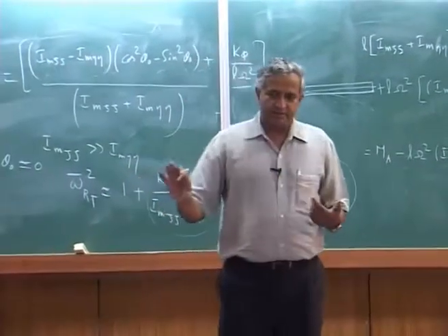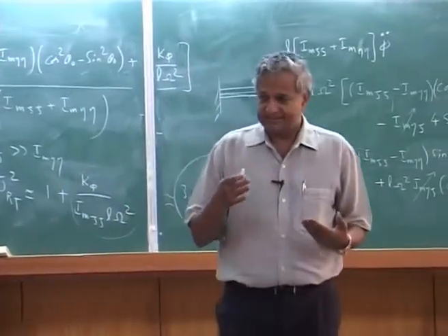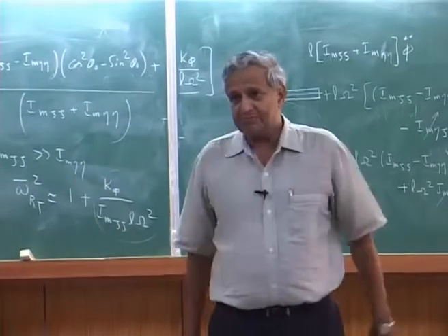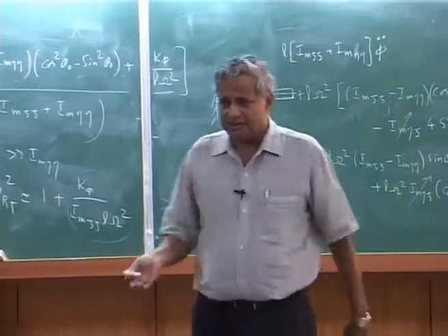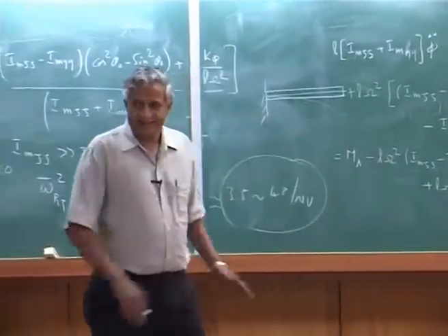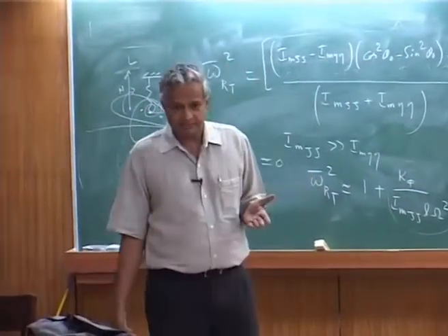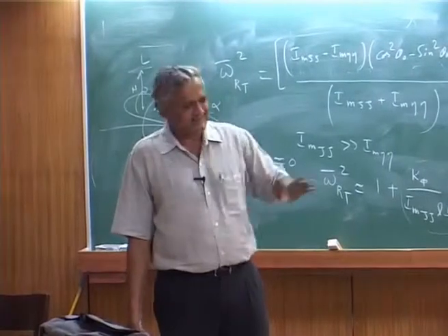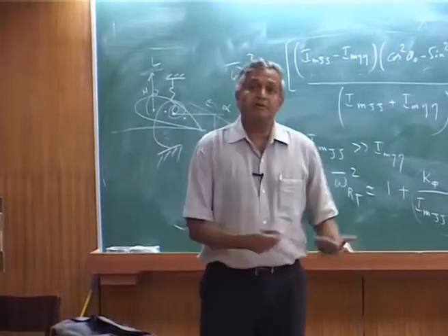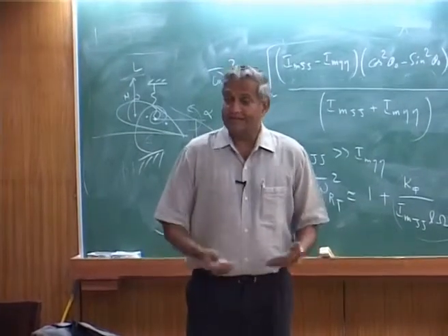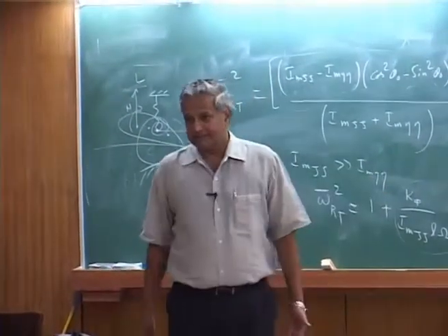Nobody uses CFD for stability problems, because then you have to do time domain integration and then try to predict the damping, etc. I have not seen any publication on that. They try to use it for loads but not for stability. These are differences, because this is going deeper into the modeling and then predicting what is happening.